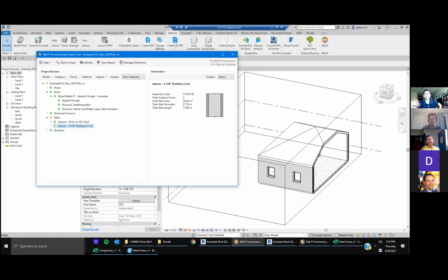But I think that's a great point. And the other thing that I'm really obsessed with, and it's very complicated, is how much does your building weigh? How do we make it lighter? There are a lot of things that we add on for operational use, which we're not looking at the embodied impact of. And I won't go into my rant about shades, where people are shading the windows, putting aluminum shades on the windows. But the embodied output for making fresh aluminum shades versus the operational energy to cool your building: the payback period is like 60 years for those shades to make up the operational energy, compared to just not having them and decreasing your window to wall ratio.